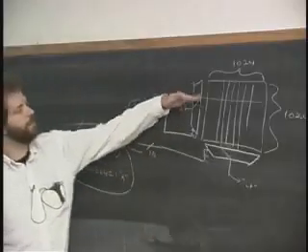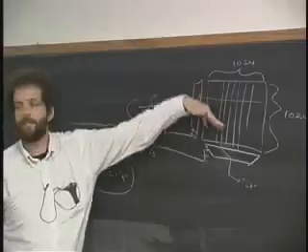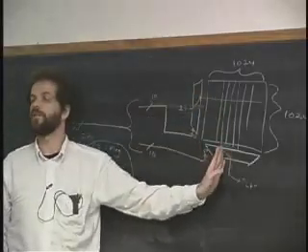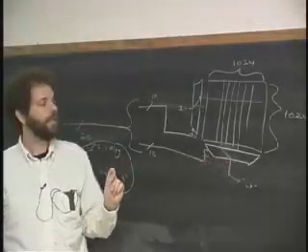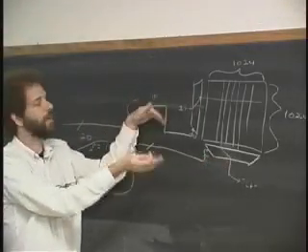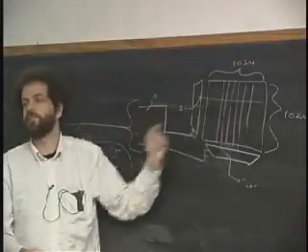So these 10 bits will be used to choose the row. And once we energize the row, the 1,000 bits that are on that row will come down, and then we'll choose which column we want, and that'll get us 1 bit. And there are 2 to the 10th times 2 to the 10th, or 2 to the 20th, different possibilities of choosing a particular bit out of this matrix here.